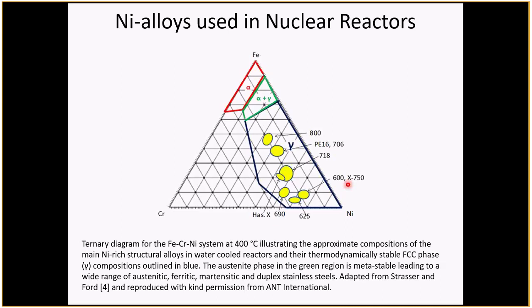also the gamma prime, these precipitates, the gamma prime precipitate in particular, are what you get in superalloys. But generally, the superalloys refer to those alloys which contain a lot of gamma prime. Again, I'll talk about the gamma prime in a second. Alloy 600 tends to be used in steam generators, just like 800.